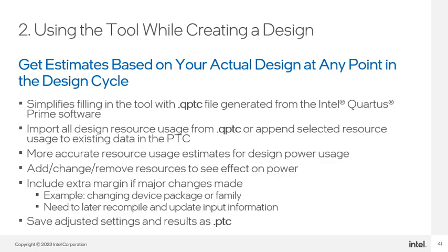You can start a new calculation based off the data in the .qptc file, or you can append selected information from the .qptc file to your existing power calculation. You can still add, change, or remove resource information from the PTC as you like after the import to see the effect on your design's power usage.